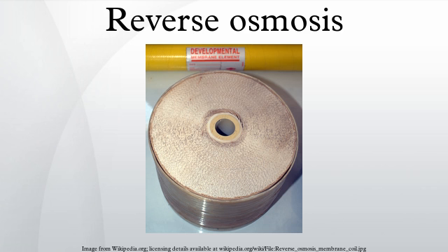Membrane assembly. The membrane assembly consists of a pressure vessel with a membrane that allows feed water to be pressed against it. The membrane must be strong enough to withstand whatever pressure is applied against it. Reverse osmosis membranes are made in a variety of configurations, with the two most common configurations being spiral wound and hollow fiber. Only a part of the saline feed water pumped into the membrane assembly passes through the membrane with the salt removed. The remaining concentrate flow passes along the saline side of the membrane to flush away the concentrated salt solution. The percentage of desalinated water produced versus the saline water feed flow is known as the recovery ratio.